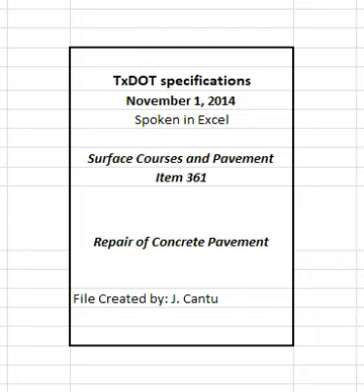Obtain approval for the repair material mix design. The selection of repair material should be based on the time for opening to traffic and temperature range during the repair. 2.2.1 Hydraulic cement concrete for pavement.